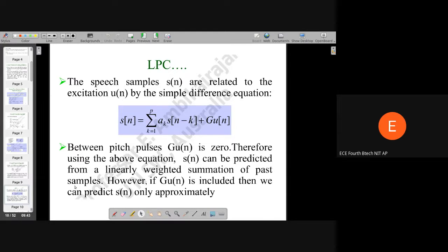Plus you can have some real poles and so on. So there is a heuristic method of figuring this out. If you are thinking, let's say, an 8 kilohertz signal means 4 kilohertz maximum frequency, for each 1 kilohertz there is one resonator. So eight poles within 4 kilohertz, plus we add 3 or 4 more poles for modeling the spectral slope.